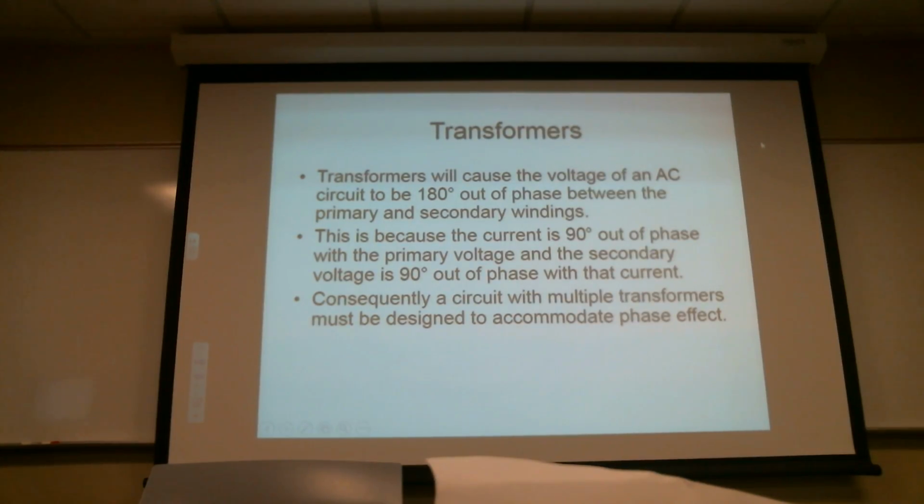And I'm coming back into the rest of the circuit. The other two leads are 277, right? Now I've got two leads of 277 that are exactly 120 degrees out of phase with each other like they belong, but the third one has been shifted because of the extra transformer in there. It's been shifted 180 degrees out, okay? Which means ultimately it's 60 degrees off of where it's supposed to be. So I'd end up having 120, 120, 60, and then a big gap of 180 till the next phase comes back on again.